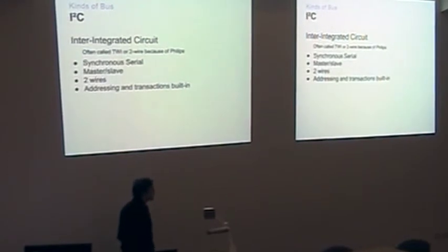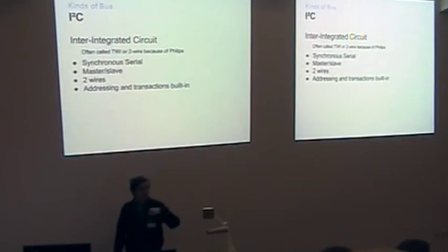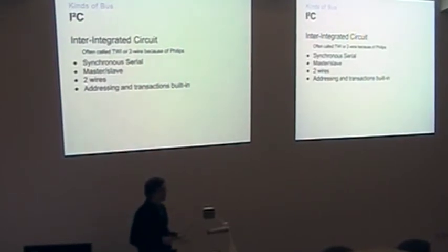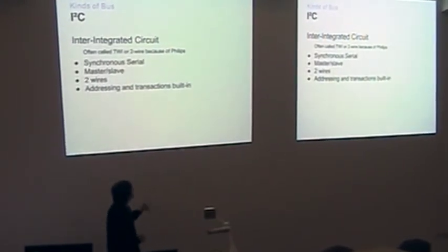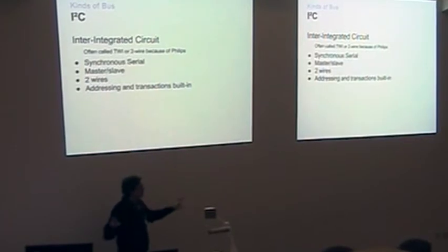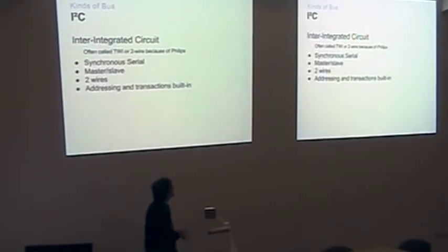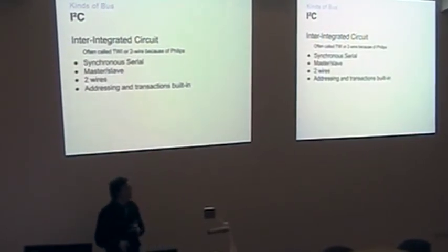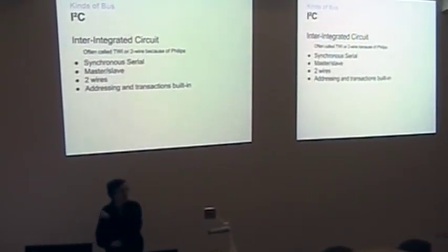As compared to SPI, in SPI, you send one wire per chip that you're going to talk to. So the master can say, you, and you just hit that one slave line. So all of the protocol is very simple. In I2C, the whole thing is a shared bus, and every device has built into it an address, an idea of what number it is, which makes things both simpler and more complicated. It's simpler because all you have is two wires that are shared everywhere. It's more complicated because each device has its own idea of what its address is.